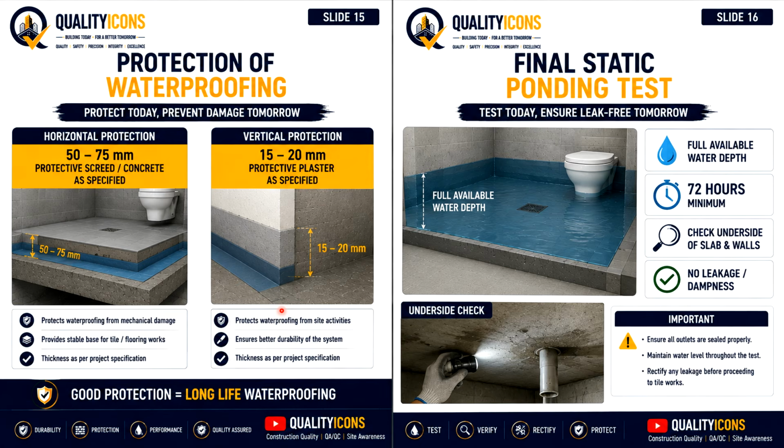Now comes the final static water ponding test. After completion of the protection plaster, water is maintained at the full available depth for 72 hours as per the methodology presented. The underside of the slab and the surrounding walls are inspected for leakage or dampness. Please remember, the underside of the slab and the surrounding walls are inspected for leakage or dampness. Only after satisfactory inspection should the area be released for the next activity, the tiling works.